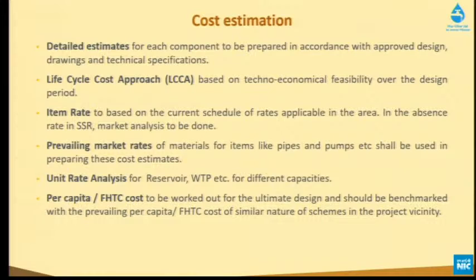About the cost estimate, we have discussed a lot about the design. If we have a very sound design and good technical specifications, our cost estimate is going to be right. So when we do the cost estimate, make sure that we have good design and technical specifications. And again, about the life cycle cost approach, it's not only the capital cost. When we are taking any component, see what will be my cost in the long run, considering a design life of 30 years, and based on that we should make the selection. Item rate is well known to us. In most states we have the SSR rate. In case we don't have it, we can use the market rate to determine the cost.